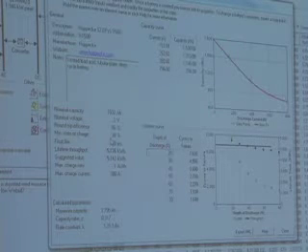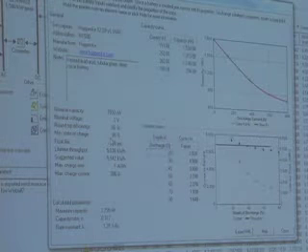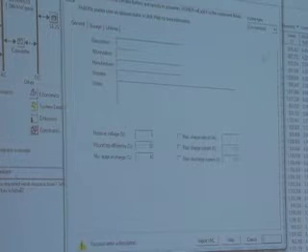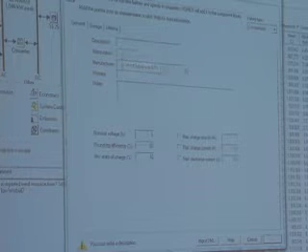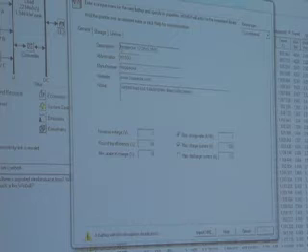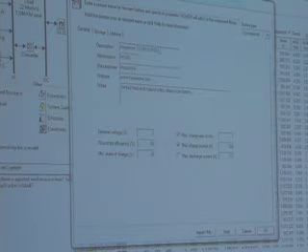If you want to change the minimum state of charge of the battery, you have to create a new battery that's identical to the other battery, except you can change this one parameter. So I should perhaps show you how you do that. Go into New, give it a name. Wait a minute, just a second here. Actually, we go into, let's say we take copy. Okay, this is identical. We'll change it to, instead of that name, we're going to give it this name, but we're going to call it a 40% SOC.